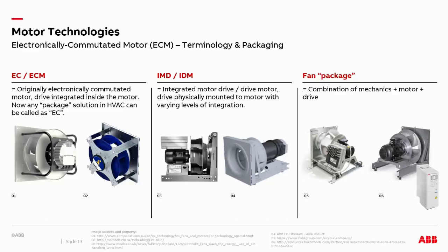So generally speaking, the integration of a PWM, pulse width modulated drive, into a fan motor drive package is generally considered to be an ECM. But as you can see in these pictures, they come in different shapes and sizes.